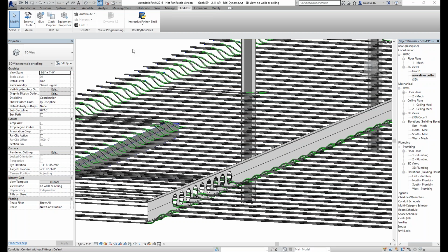Another question was, what happens if the batch file is run without deleting the original routes? Well, if you run a batch file and you already have the routes in there, obviously they're an obstacle in the way, so it just won't route. We have seen, and this was kind of an error, a funny thing where it routed around the other side of the conduit if there was nothing on that end or the pipe. But yes, if you run the batch file again and it already has a route there, it won't route because there's something in the way.